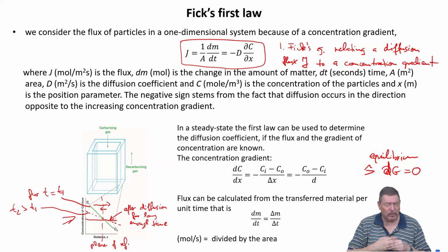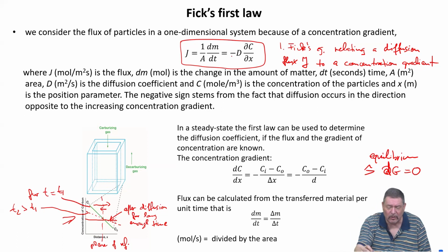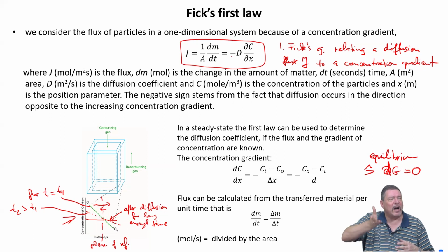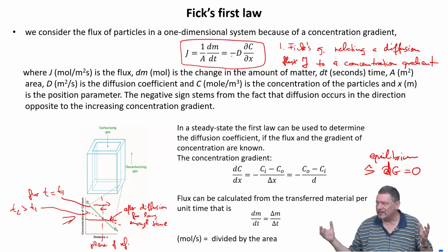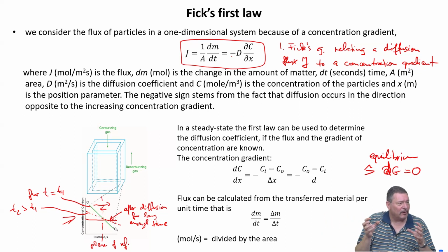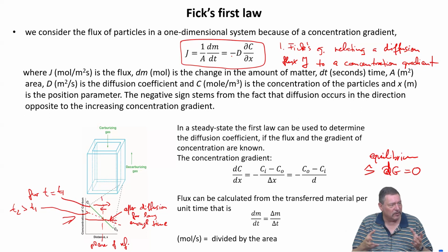Well, that's difficult to say because it depends really on the kinetic constant, which is the diffusion coefficient D. And it depends a lot on temperature because D is a strong function of temperature. So if you go to higher temperature, the time will be shorter. And for different systems, carbon is a fast diffuser in iron because it's an interstitial diffuser, so it will take less time than, let's say, a cobalt gradient in iron, because of substitutional diffusion, and it will take at the same temperature much longer to equilibrate.